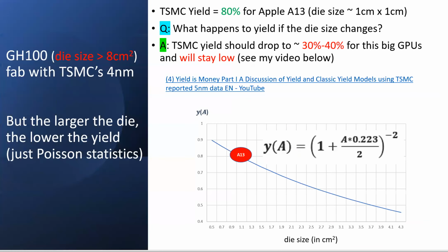The second review I'd like to present here is that the die size really matters. The die of advanced node is getting larger and larger. Look at this simple calculation I have done before for you. It's going down. So the key message is that the larger the die, the lower the yield. It's just about some statistics about particles landing on the wafer killing the die.